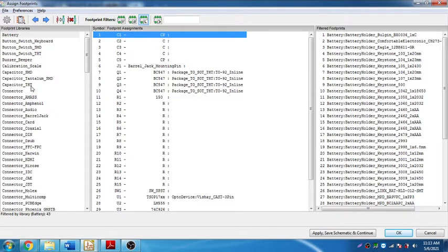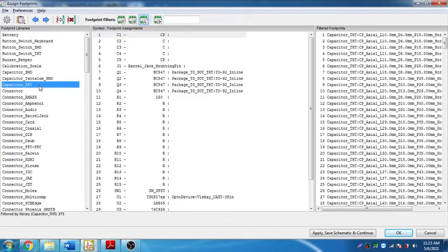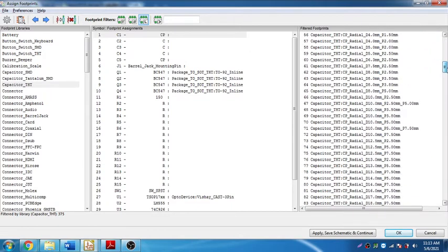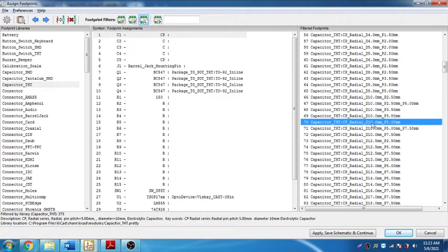So what you need, and I'm going to search it in the through hole component now. So under through hole component, you need to search the footprint for this, and under radial. Okay, I will search it under radial. I think we will go with the radial footprint where the diameter is 10 and pitch is 5 mm, which is enough for this.